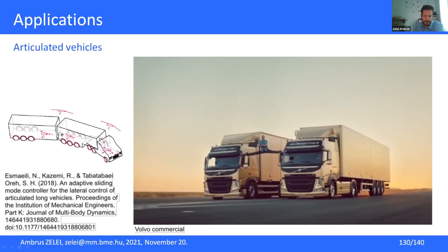Here there are only 2 actually. But you can have just 2 control actions, the steering wheel and the gas pedal, and that's it. So it's definitely underactuated. Actually, the problem is that there are also some kinematic constraints here. If you have a car, it's not 3 degrees of freedom in the plane, it's just 2.5. And this is again another problem.